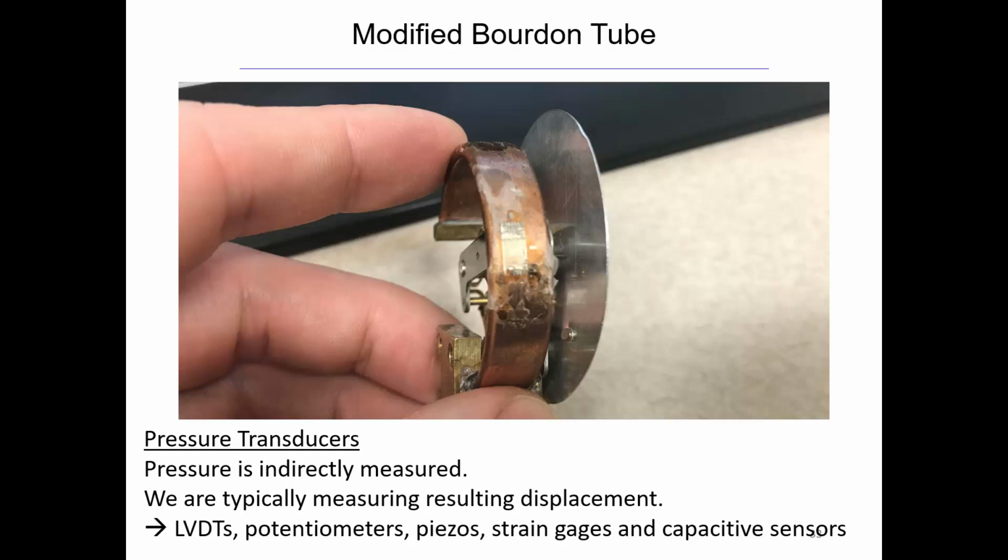You can always get a soldering iron, and you can order these strain gauges for a few dollars each. You can get a Bourdon tube from Home Depot for a couple dollars. Maybe you have a compressor lying around, or you can borrow one from somebody. So you can try this out yourself. I guess the DAQ part might be a little bit difficult, but you could always just get some fixed resistors and use a multimeter. You might have that lying around. It's not too expensive. If you're really motivated, you could find a way to do this yourself.